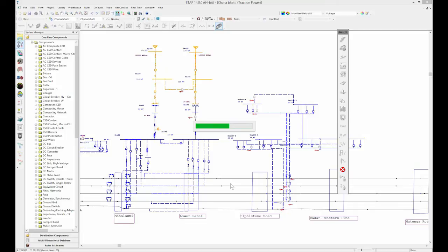It essentially accelerates the train in the system based on the limits that have been provided, such as the speed limit, as well as the time frame in which the train must go from one station to another station. So it's essentially solving the train performance calculation equations in the background, and then sliding the load across the rail.